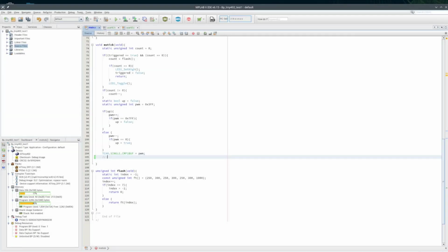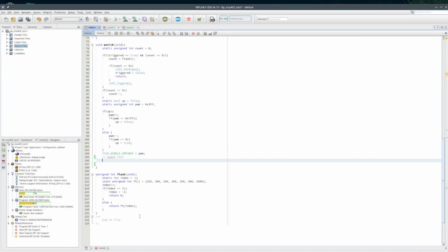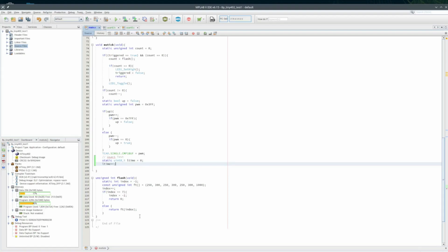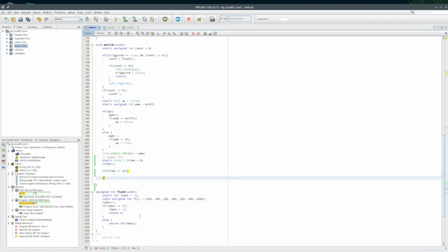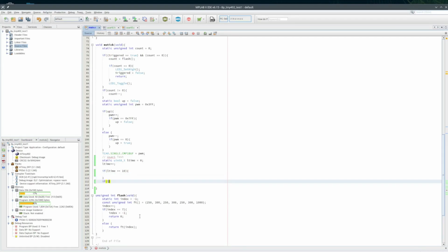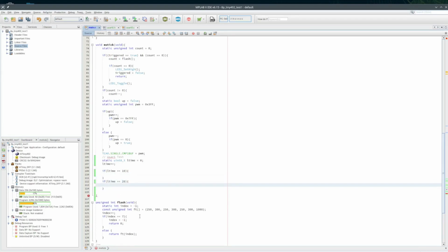So I'm going to need a bit of code to send the data to the serial module, as I will send it as ASCII characters. The receiving end is expecting ASCII text, so that's what I'll send, just to make life easier. I can send no more than 8 bytes at one time, and with a 38K baud rate, say no more than 3 bytes a millisecond. So I'll just send the data every 20 milliseconds.